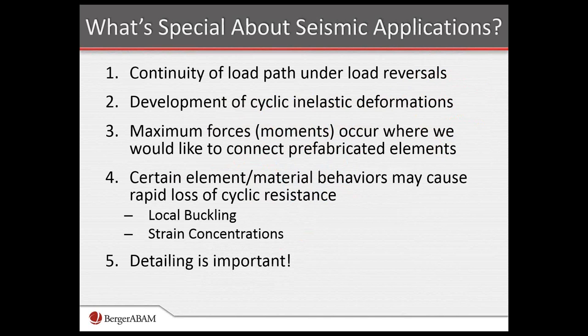So what's special about seismic applications? Well, certainly we expect that we're going to need continuity of load path under load reversals. So that means we need to be able to transmit lateral load from, let's say, the point of generation of that, which would be the inertial mass points in the structure, superstructure, for example, down into the foundation.